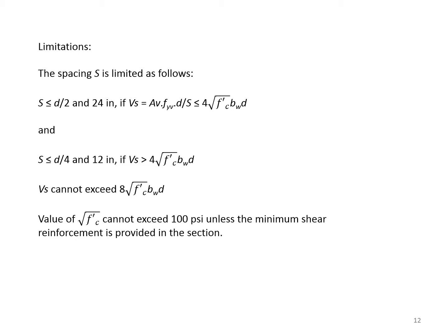Furthermore, the value of square root of f prime sub c cannot exceed 100 psi unless the minimum shear reinforcement is provided in the section.